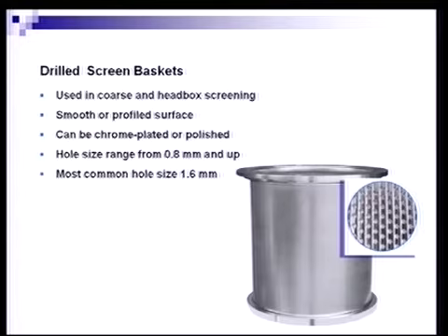And we have corrugations on the surface in order to provide micro turbulence, which gives us better consistency and better flow characteristics. Remember, we get more flow with a turbulent flow than we do with laminar flow. So we want to stir that surface up. And using these corrugations in the screen plate design is one way to do it.